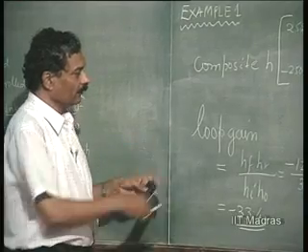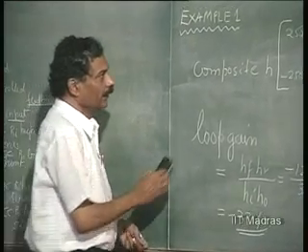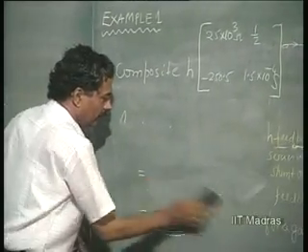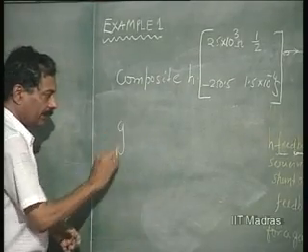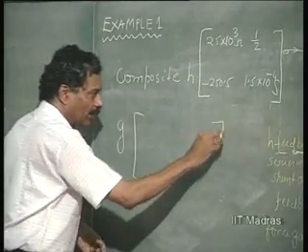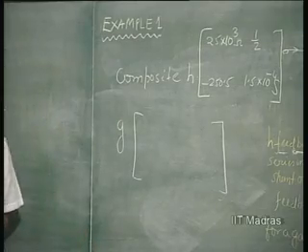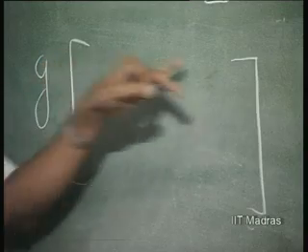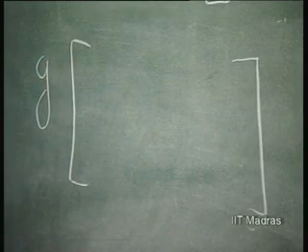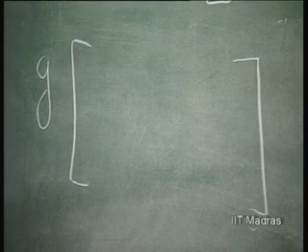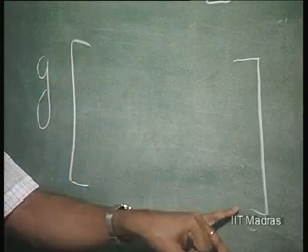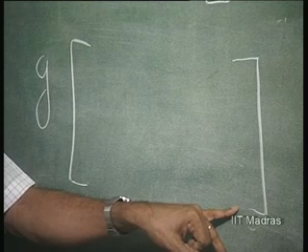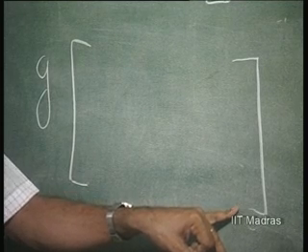So, now that we have found out the loop gain, okay, let us find out the composite G parameter, which will clearly tell me whether it has gone towards idealization. If it has really gone towards idealization, these factors should be closer to 0 than before. This was anyway 0. These two factors will go closer to the 0 than before.